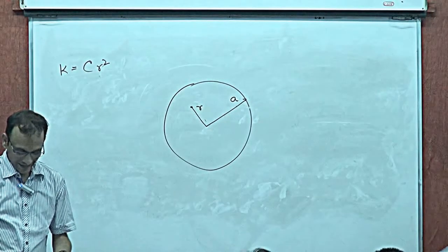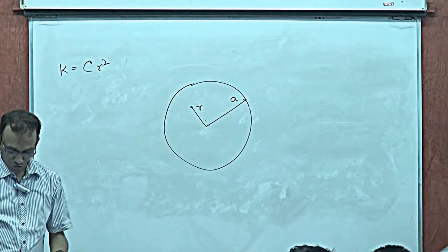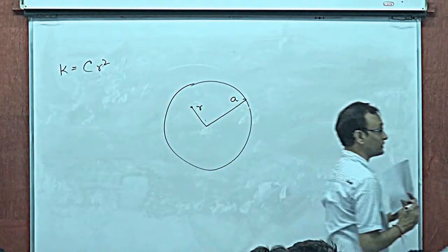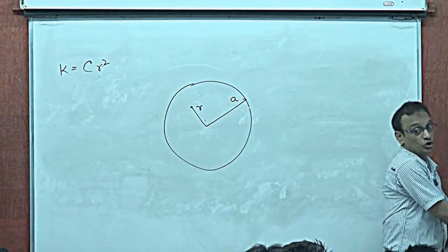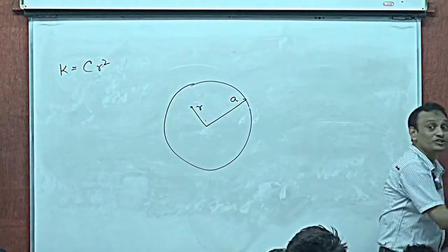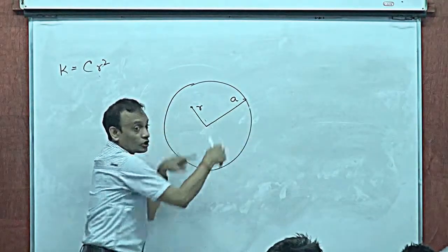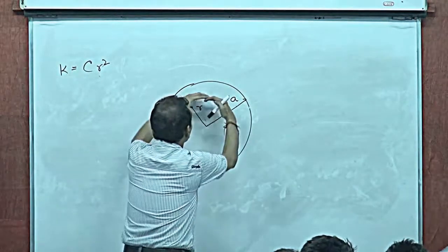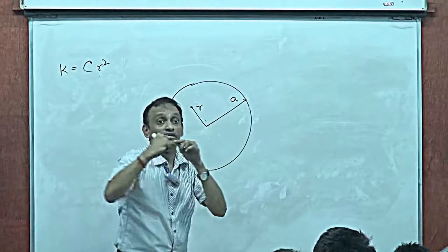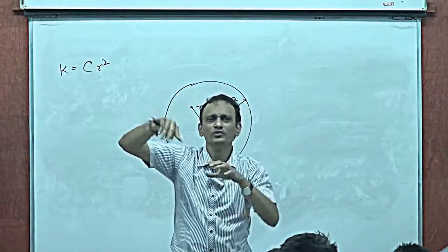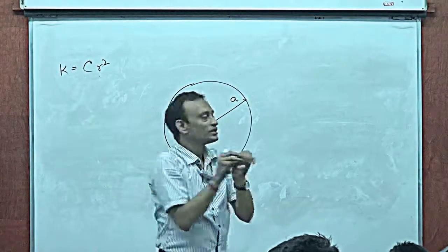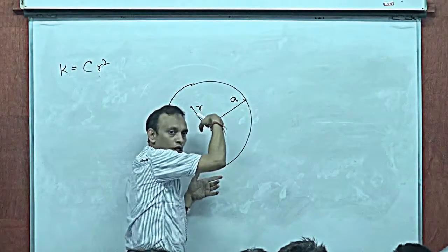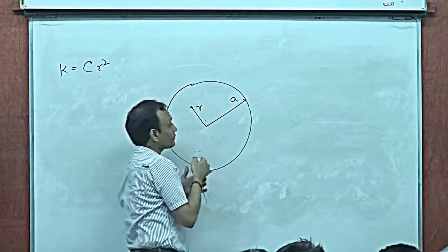Calculate the temperature gradient if the rate of flow of heat through the rod is H. Now, one thing, this is not radial flow of heat. This is longitudinal flow of heat. In any given cross section, the flow of heat is still longitudinal, but the thermal conductivity in a given cross section is varying with r. This could be a complex material whose thermal conductivity is varying in r. The flow of heat is still longitudinal, right? You know what I'm saying?